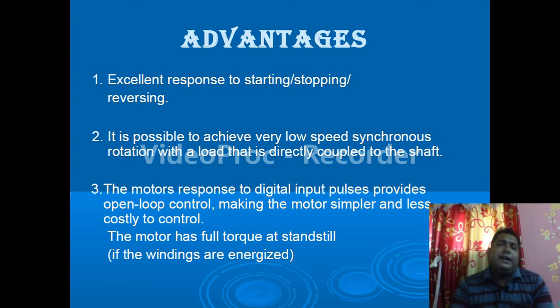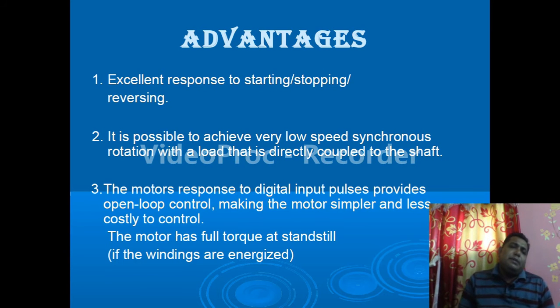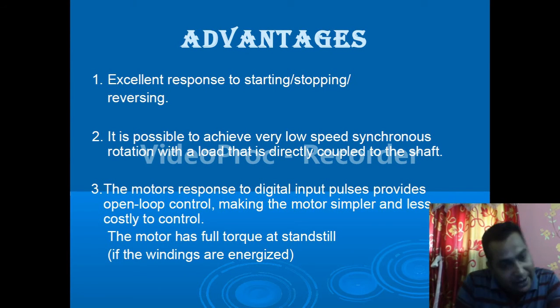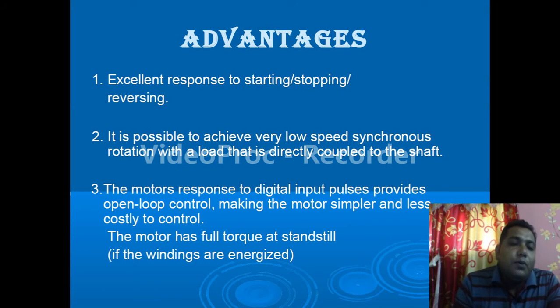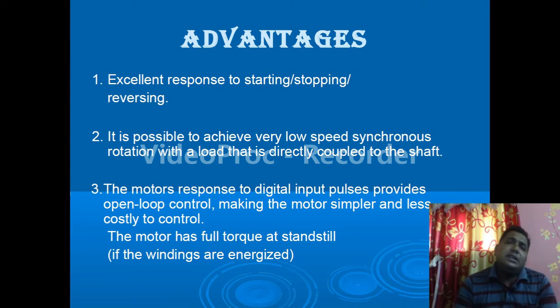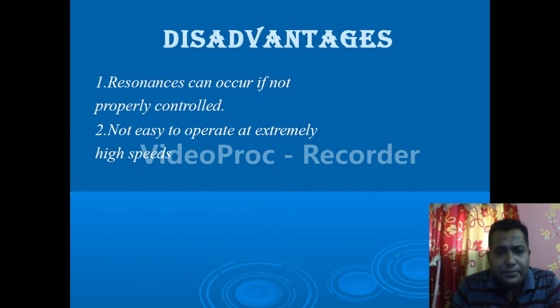Okay, let us see the advantages. What are the advantages of a stepper motor? Excellent response to starting, stopping and reversing. It is possible to achieve very low speed synchronous rotation with a load that is directly coupled to the shaft. The motor's response to digital input pulses provides open loop control, making the motor simpler and less costly to control. The motor has full torque at standstill. So these are the advantages we have in the case of a stepper motor.